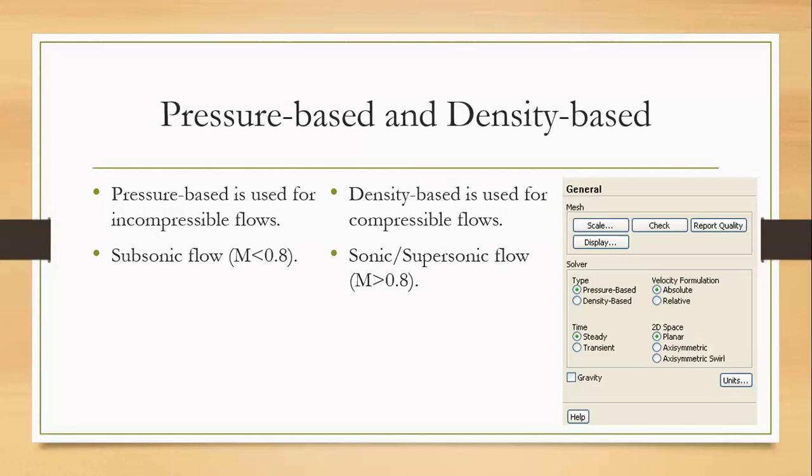And I would like to clarify here that it does not mean that we cannot solve any compressible flow problem with pressure-based, or that we cannot solve an incompressible flow problem with density-based. We can do it with either of the solvers, but it may give us some convergence issues. It will produce divergence. I'm speaking this from experience. So yeah.